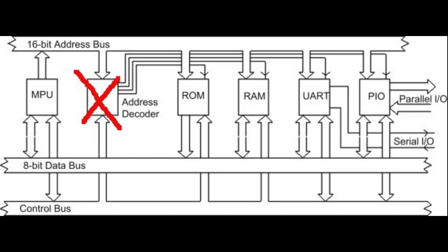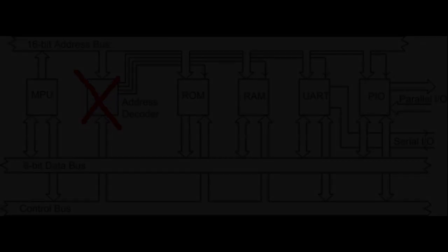What happens in this case is that more than one chip writes on the data bus, and the data bus also gets trashed because the signals have no meaning. It's also a kind of noise, and so the CPU cannot execute anything.